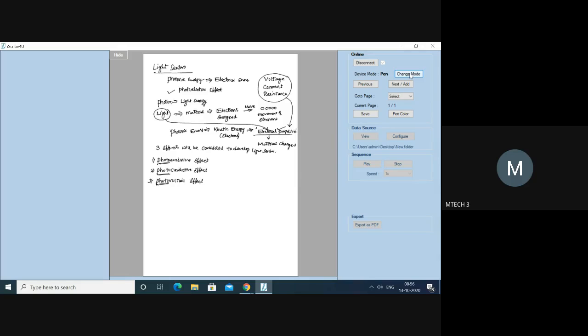Next, we understood the three different effects. If I develop a sensor using the photoemissive effect, those sensors are called photoemissive sensors. Then there are photoconductive sensors, due to the photoconductive effect, and the photovoltaic effect leads to photovoltaic sensors. So these are the three types of light sensors, used with these different effects. Is the basic thing clear to you now? Shall we proceed?